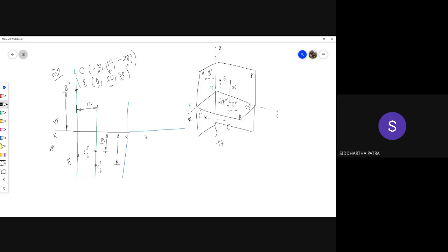Acha. So when you are doing the aligned method, the thing is, in aligned method, you are either looking at the drawing from the bottom or from the right, and when you are, let's say, looking at it from the bottom or from the right, you should write the dimension itself above the dimension line.